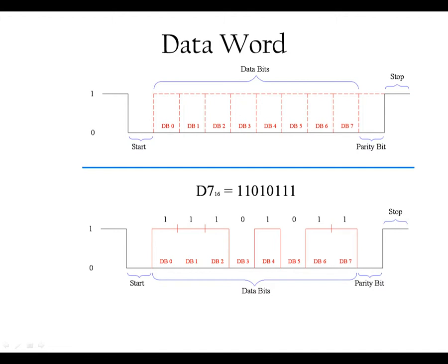In general, when there is a communication line, in general it's always high. Okay? So whenever the line is a constant high, the receiver knows that there is nothing being sent. But before you start, you always start with a bit 0. You know what I'm saying? Because that's how the receiver knows something is coming right now. So that's why the start bit is always 0, and there is a stop bit which is always 1. So we add the start bit and stop bit. We also sometimes add a parity bit. If you see, at the end of the data, we added a parity bit.